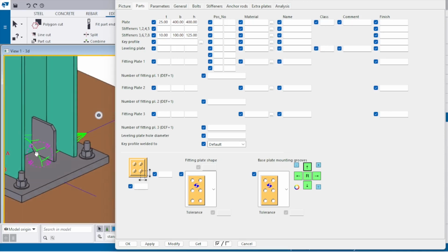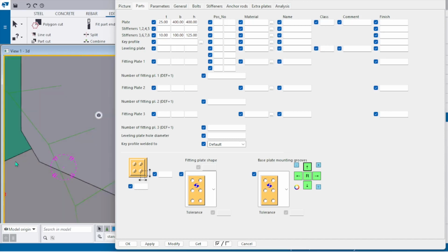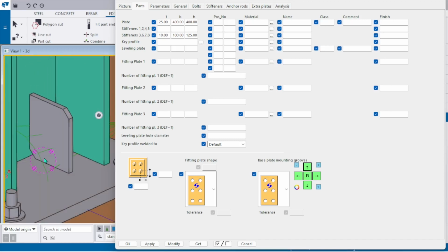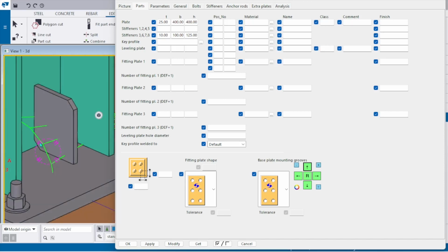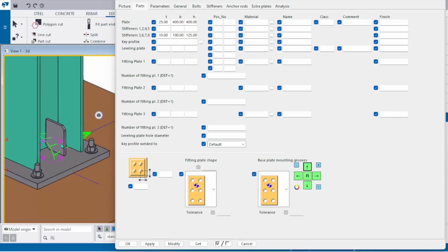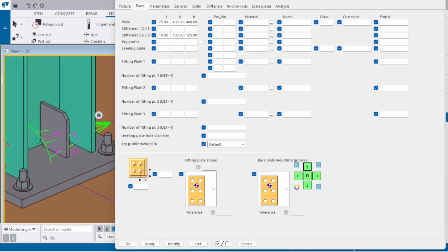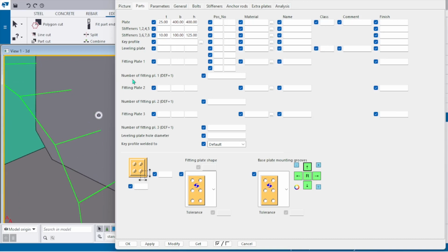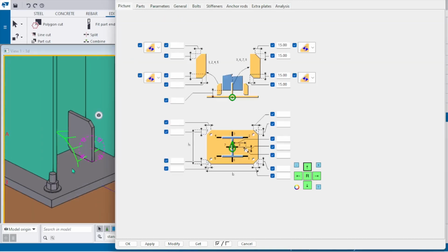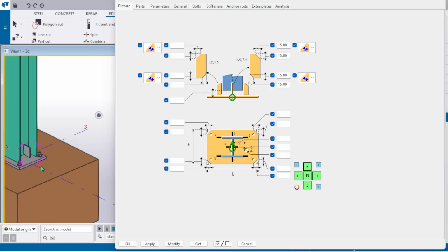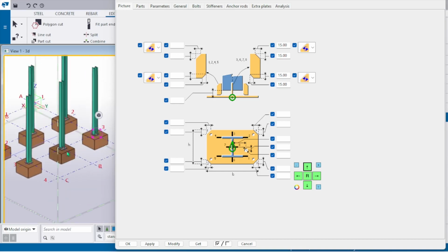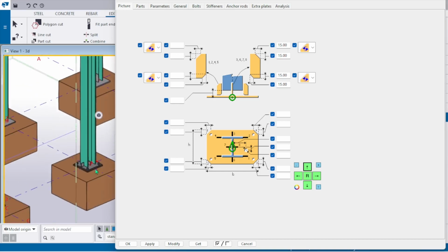Later, when the base plate is welded, in this location we need to have some holes, and sometimes all these columns and mainly beams, everything will be galvanized, so the galvanizing paint must go inside this area. So for this sake we also have to put in the gap. Normally we put in 20 mm, 15 mm, as per the requirement. All right, so this is how we do base plate and footing and column.